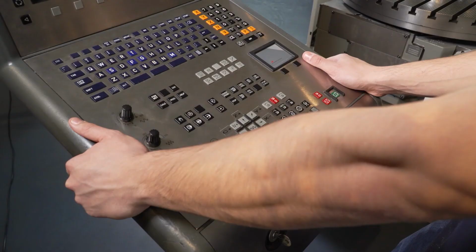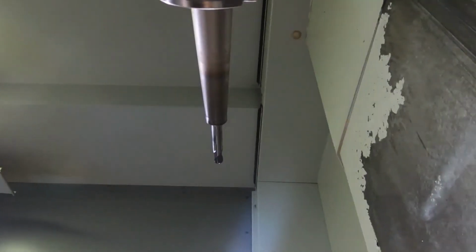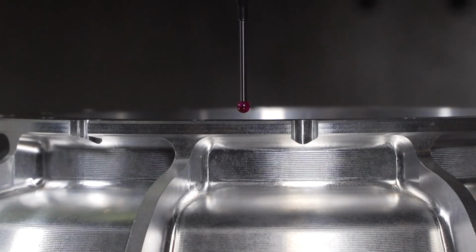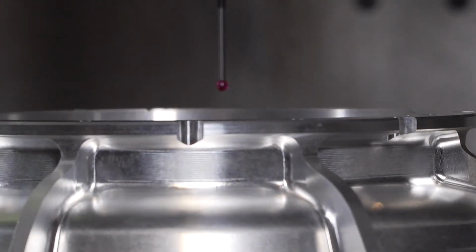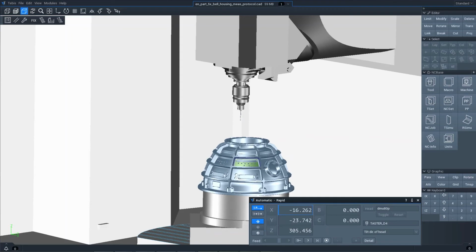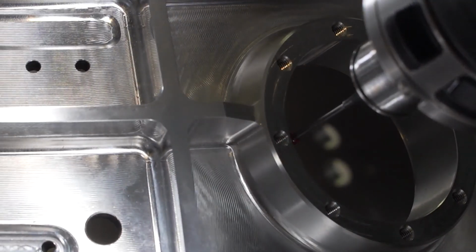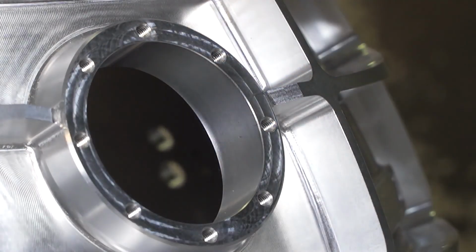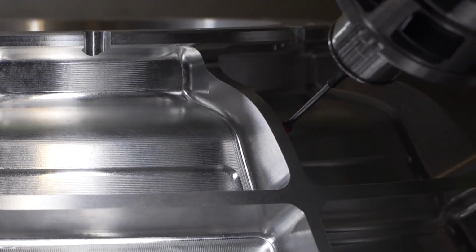I have made a little video on our DMU ATP machine, and within this video you see now how tool change is done, and the probe is now loaded, and here we have a part which we have produced for a measurement exhibition, and we are of course using these parts also for testing our own software. And here you can see the simulation, which is working as well in Tebis, and here the real movement of the machine for a circle measurement in this circular pocket here. With the tilted tool, of course, now the tilting direction is going to change. Simulation and collision check has been okay.